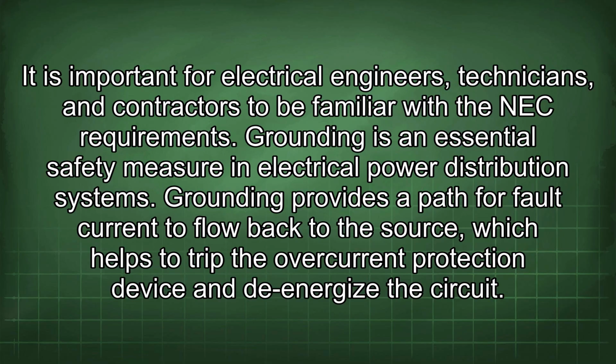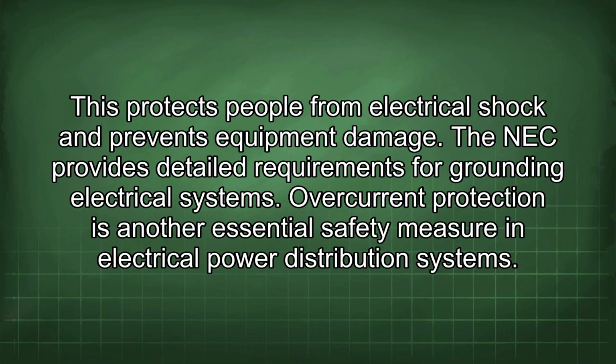It is important for electrical engineers, technicians, and contractors to be familiar with the NEC requirements. Grounding is an essential safety measure in electrical power distribution systems. Grounding provides a path for fault current to flow back to the source, which helps to trip the overcurrent protection device and de-energize the circuit. This protects people from electrical shock and prevents equipment damage.